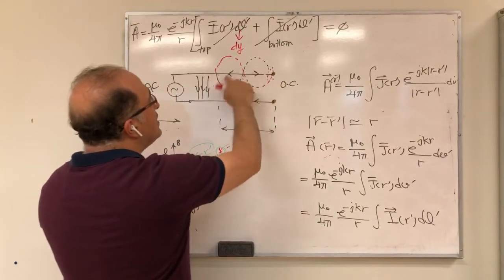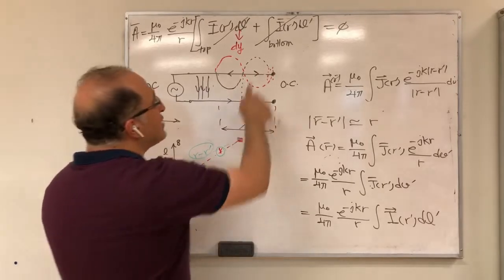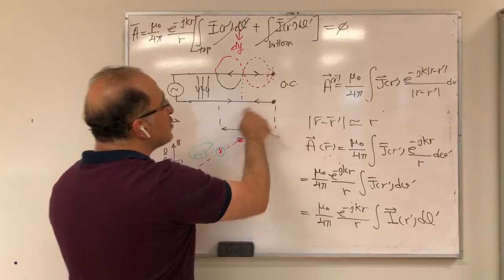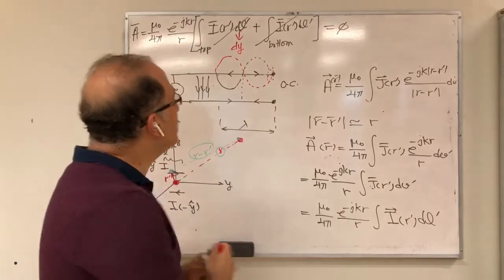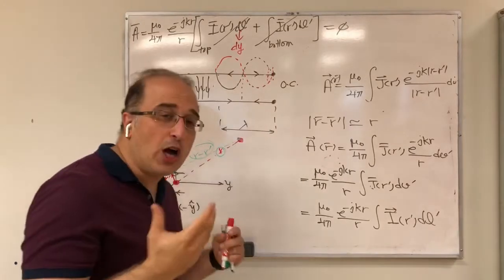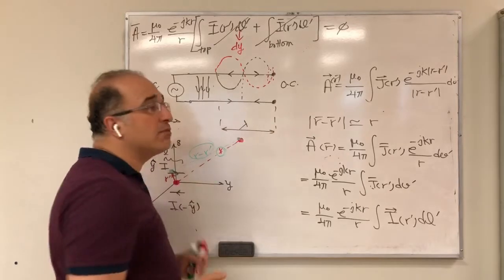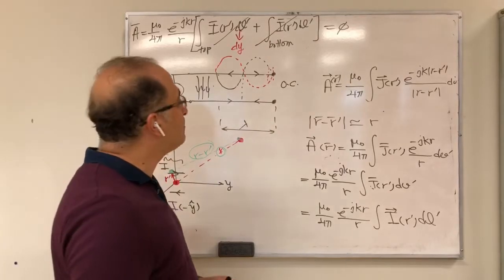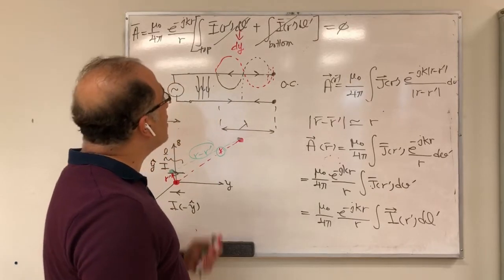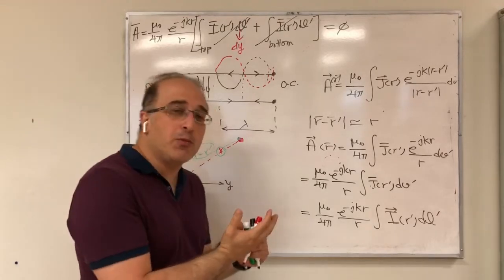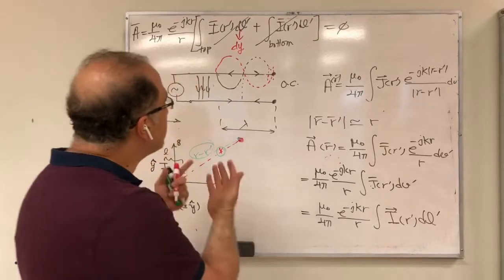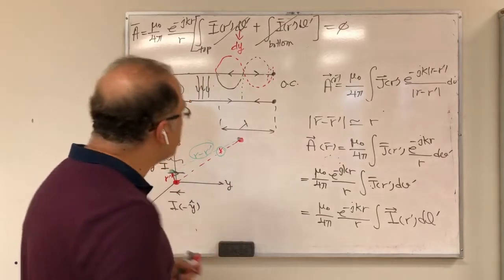So essentially, these would be reversed. But the point is, as soon as this is reversed, this is also reversed because that's essentially your transmission line. So the direction that I choose does not matter. It's the relative direction between them that matters. So that's our discussion based on magnetic vector potential, that why these transmission lines do not radiate for us.